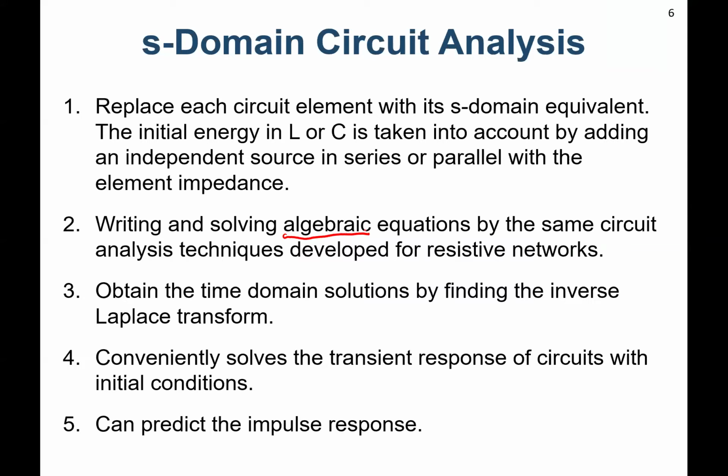So we're going to actually do the same thing that our colleagues in ECE do. And we're just going to do things and solve them algebraically. No differential equations. If you want to do differential equations, that's fine, but you're going to find out they're much easier to do algebraically, even when we do partial fraction expansion. So we've got algebraic equations, and we use the exact same circuit analysis techniques that we do for resistive networks. Once we're in the Laplace domain, capacitors and inductors just look like resistors. You treat them exactly the same as resistors.